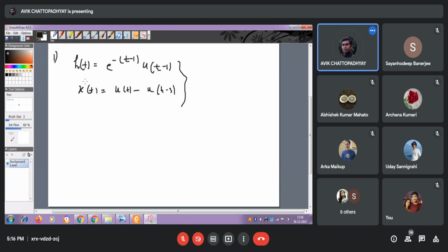So again, we have to do the convolution, but first you have to draw the corresponding pictures, the waveforms for h(t) and x(t), and then you do the rest of the operations. Please note, you have to apply the graphical method, step by step, graphically. The pictures you have to draw are for different steps or ranges, whatever you take. Show the overlapped portion, etc. So graphically you have to do the first thing.